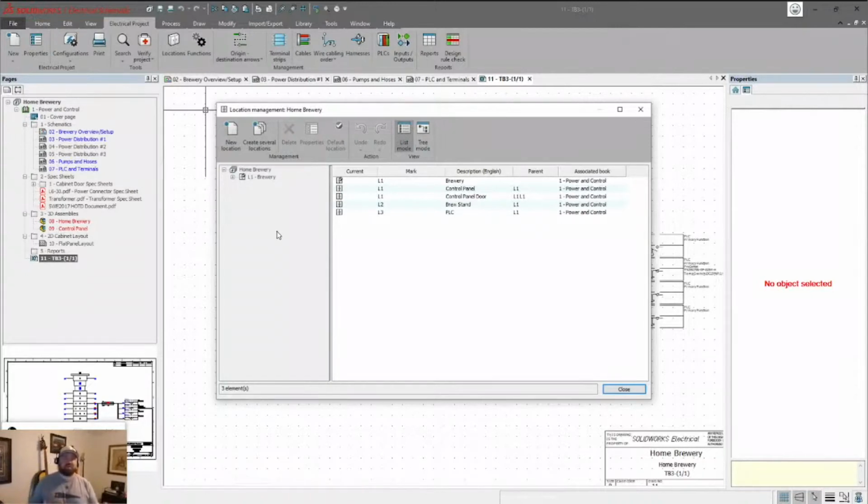But then as time went on, I was like, well, you can actually set up your projects based off of these locations and assign your top level assembly on the 3D side, and all your sub assemblies to different locations. And the reason I would recommend doing that is setting up those different sub-assemblies. Let's say you're working with a crane and you have the cab for the crane, right? That could be one sub-assembly. Within that cab, then you have the chair, maybe that has its own sub-assembly. So you can create a location for each one.